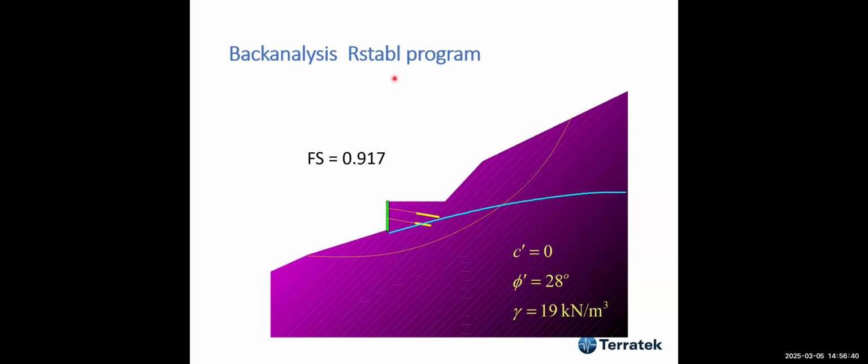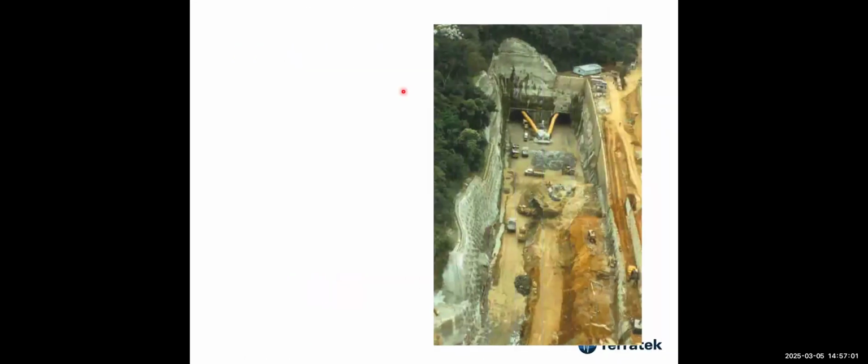This was the main cause of failure. And I did this with a program that I wrote, not all the program, as a matter of fact, I used the STABL program, which was written at Purdue University. I did some modification to include the effect of nails or grouted anchors.